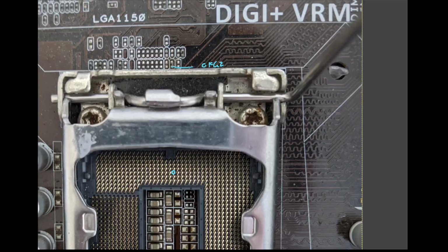Now that we have confirmed which pads on the motherboard actually map to CFG2 on the CPU pins, we can now pull this pin down to ground. Usually the best practice would be to solder a resistor onto the pads, but since this is a lab motherboard, I just added a small copper wire between CFG2 and ground in order to make this connection, as shown here.